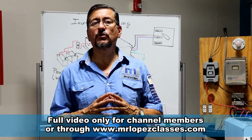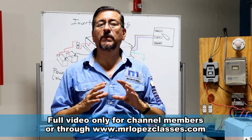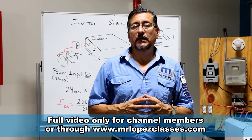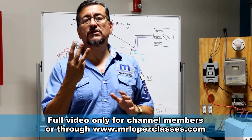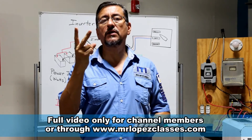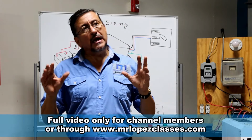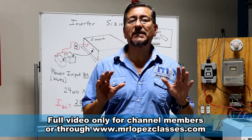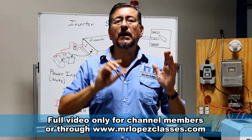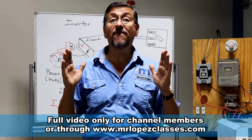I am going to explain the procedure to calculate the capacity of the inverters in kilowatts, and the procedure to install the inverter on the boat. Remember, the inverter is one of the three sources of AC power. One source of AC power is the shore power, the second one is the generator, and the third one is the inverter. The inverter has a couple of inconveniences. One inconvenience is that the output signal is not a perfect sine signal, it's like a little square, and additionally the output signal from the inverter doesn't have frequency.